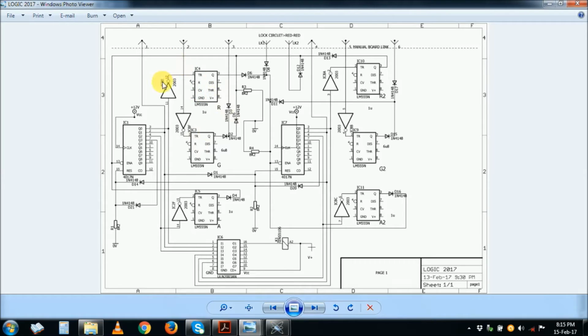And then this main board controller, which I call the logic board, it's got attachment to other boards, so it has external attachments to it for it to work. Here is the relay driver. You connect your relays here. This is the ULN 2003, 2004, 2803, 2804, or you can actually do it with separate transistors, but this is the best. It's smart, it's clean.